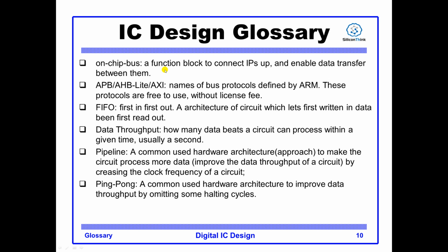On-chip bus is usually a function block to connect IPs together and enable data transfer between them. So you have to define some protocol to realize the bus. APB, AHB, AXI, these are on-chip bus protocols. These protocols are defined by ARM, and you can use them for free.